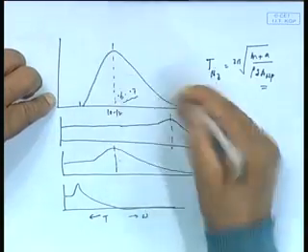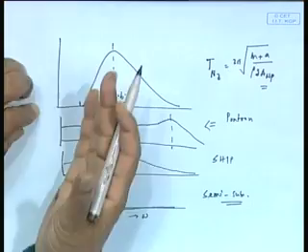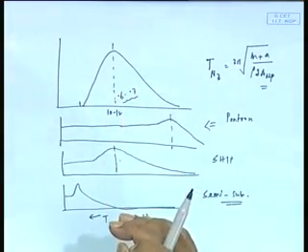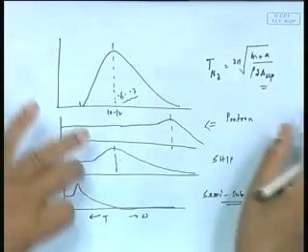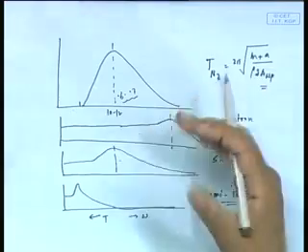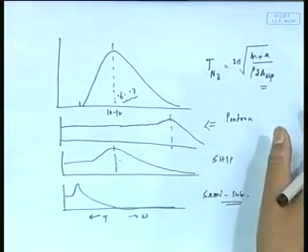So, what I was saying is that if you did those actual values of the spectrum formula with H 1/3 even up to 8 meter, you will end up getting a shape like that, it is shifting. Even though it shifts, you will find out that even for the highest wave, there are practically no waves above 20 seconds. In fact, only if you do this program and write equivalent T, you will get a physical feel about what kind of waves you find in the ocean. Offshore people call this the everyday wave. Somebody can say, well, is there no tsunami or long wave? But they are very rare. The wind generated wave given by the spectrum is like that.